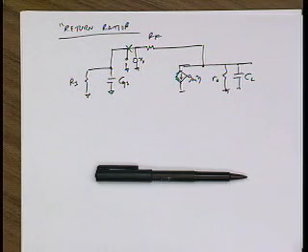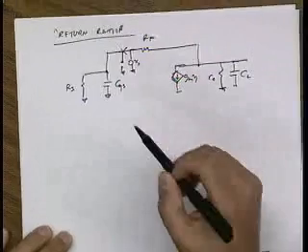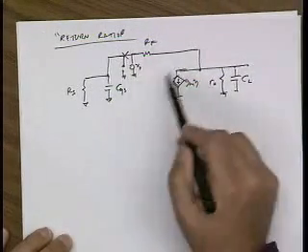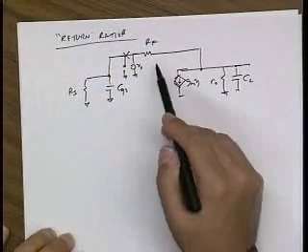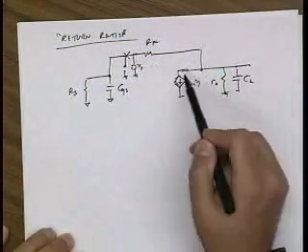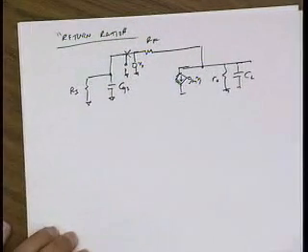Okay. Debo, I think you have a solution. Inject current. You're still going to have the same problem, right? Because if I inject current here, I still break the loop and I still have loading effects, right? So now instead of RF to ground, I have RF floating. So this part of the amplifier doesn't even see RF. So that's not good.